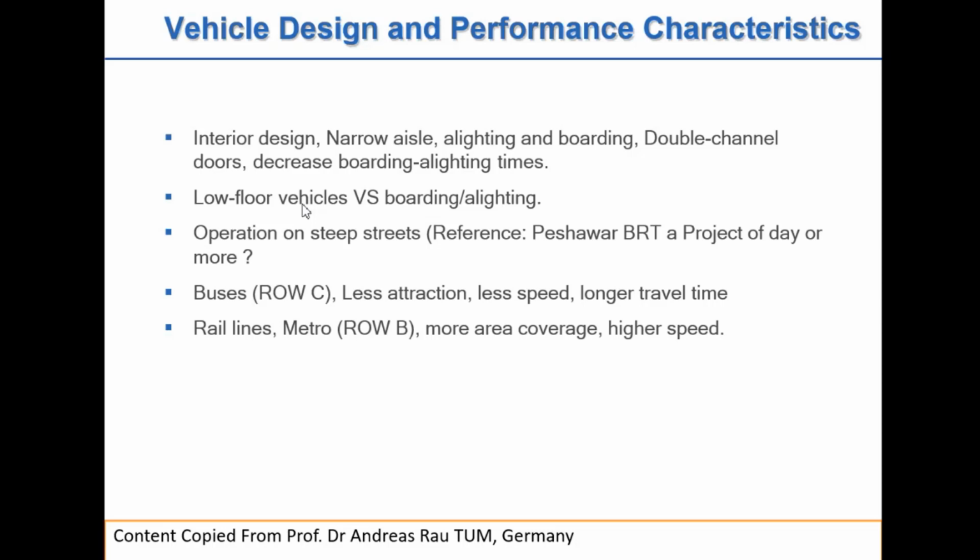Because keep in mind, we want to increase the transit speed. For example, if at any particular station the vehicle might stop for more than 1 minute, and it's supposed to stay there for like 20 to 25 seconds so that passengers can easily alight and board and then it moves on. So this 30-second delay is at a single particular stop, and in the same way it goes on. The second is we need to introduce low floor buses, because installation of a low floor vehicle usually offers faster and easier boarding and alighting facility.